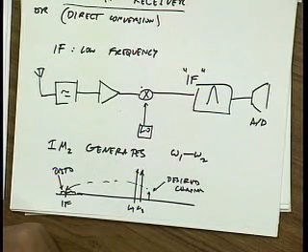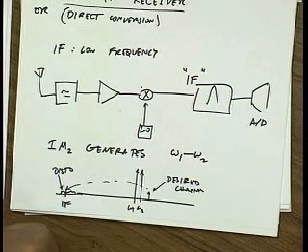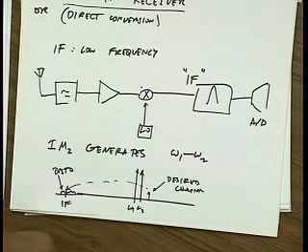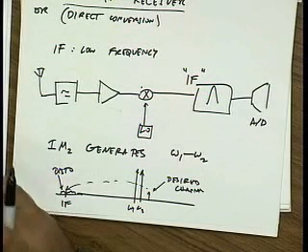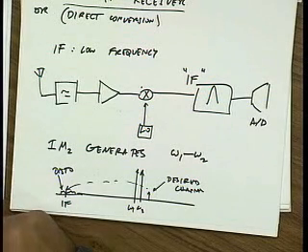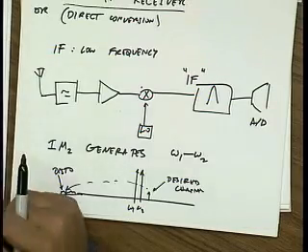Yes? Well, remember, you can never build a perfectly differential signal path. There's always going to be mismatch. So there will always be residual second order due to matching constraints. You know, in integrated circuits, you build two transistors, you make them the same size, they come out different, right? Because they're so small, there's going to be lots of variation due to doping, due to lithography, and so on.